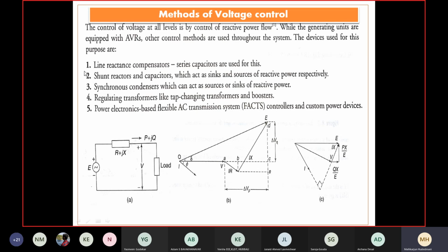That's how, when there is a need of reactive power at a particular load, it can be compensated using a shunt capacitor at that point. Or suddenly, in a highly compensated system, just imagine a long transmission line, the first case itself we can consider: a very long transmission line having series capacitor and other controlling concepts meeting the requirement, highly compensated.